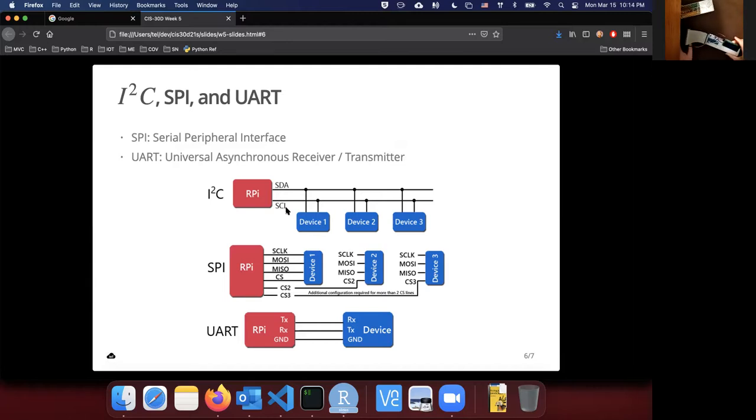If you look at the Raspberry Pi pin names, you'll see SDA1, SCL1 at physical pin numbers 2 and 4. No, actually 3 and 5. If you look at your extension board, you'll find those at physical numbers 3 and 5. Those are the 2 pins that we need to connect. When we connect, I'll explain a bit more, and let me finish this one now.